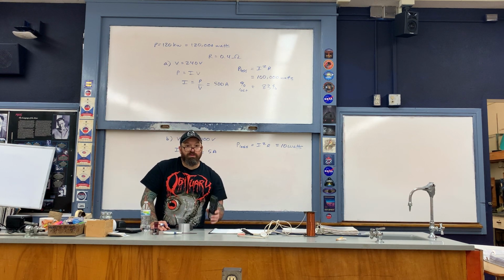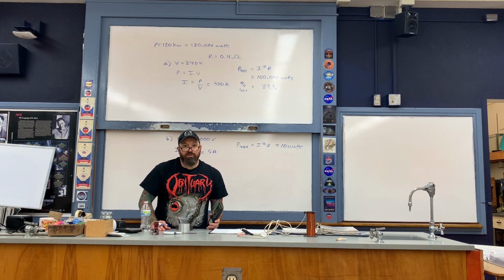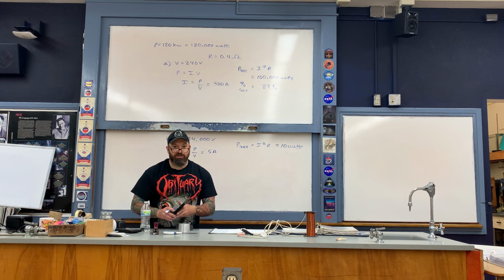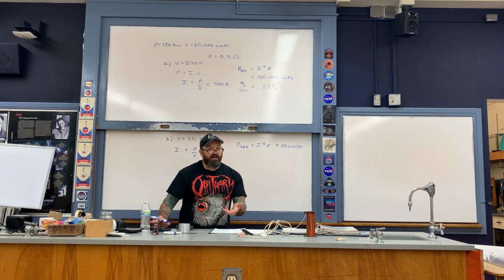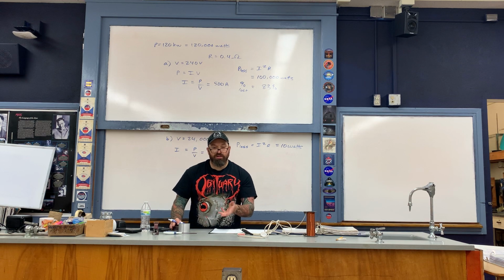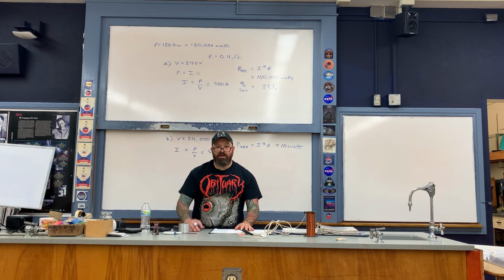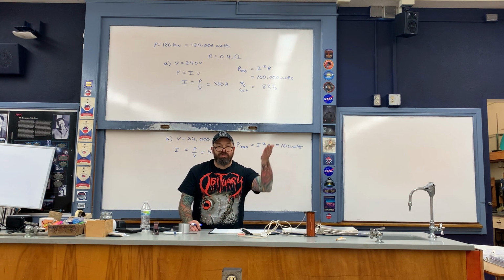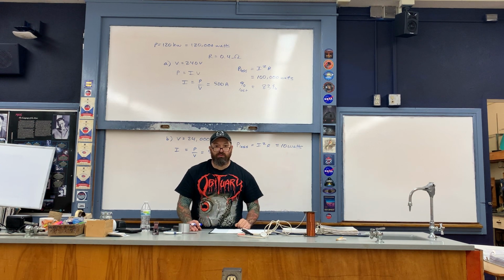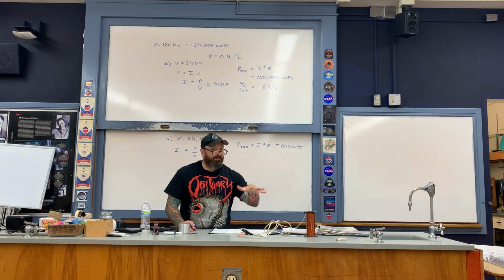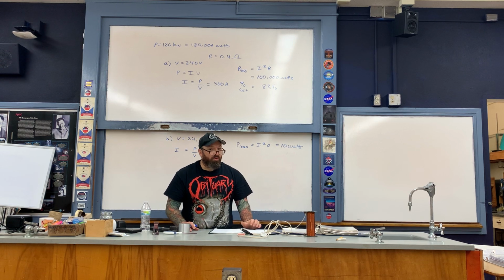So this is very nearly 100% efficient when you transmit at extremely high voltages. So the basic idea behind power transmission is as follows. You first of all, of course, generate the power at the station, and then you immediately step up the voltage to extremely high values to transmit it out to the electrical grid. But then you want to step down the voltages by using more transformers.